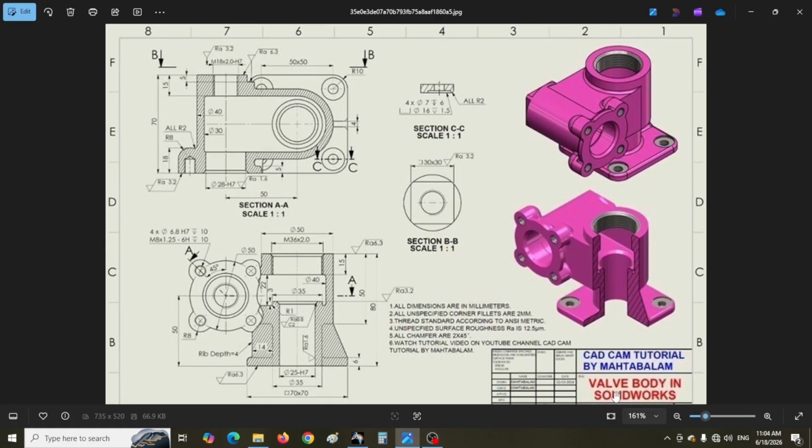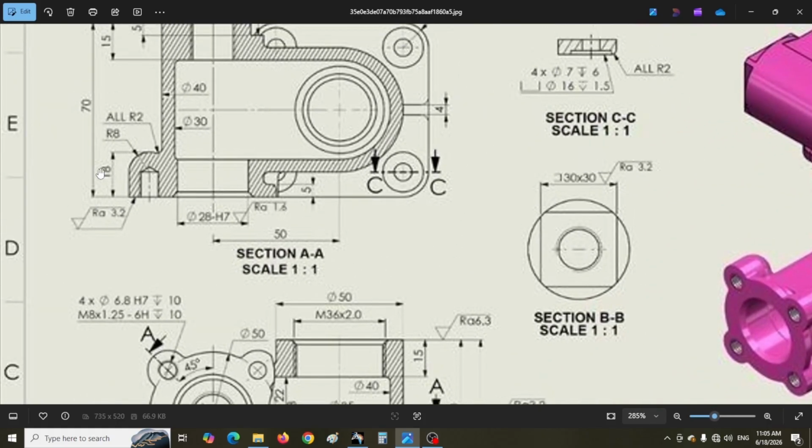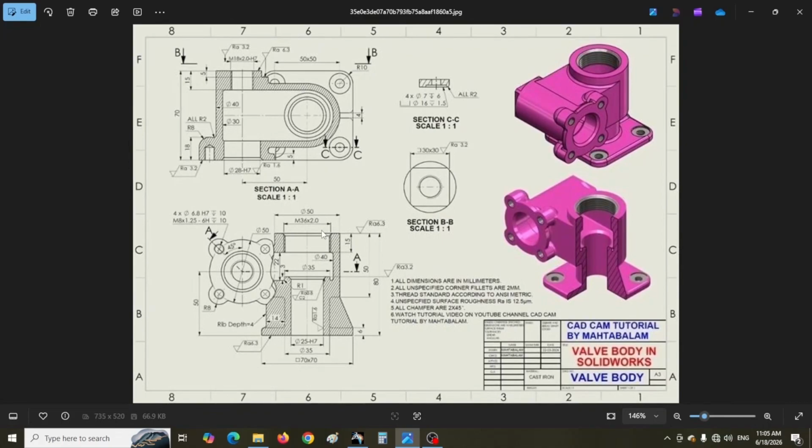Now look at the shape. There are 4 rounded cylinders around this flange. The height of these 4 cylinders is 18 millimeters, while the height of the flange is 5 millimeters. So both sketches cannot be padded together in one step.